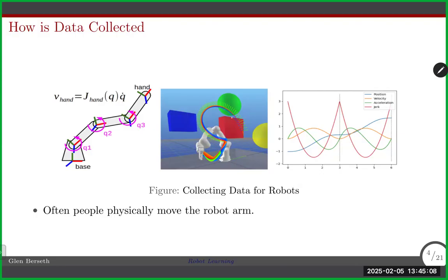If there happens to be a singularity between two of the points, it can't resolve them without sticking its elbow through a wall. So it would only ever control those things in the end. There's really no space in there to be able to adjust, certainly not to deal with contact with other items. And what was actually a new and still pretty useful design is what companies are making called cobots. Now some of these robots have an electrostatic sensing skin on them. So if they do accidentally bump into a person, they stop immediately since they don't really pay attention to anything else about what's going on. But it's not a very reactive, smooth, collaborative system. It's also extremely slow, and unless you've got a master's in robotics and really understand inverse kinematics, there can be really odd outputs and behaviors that happen.